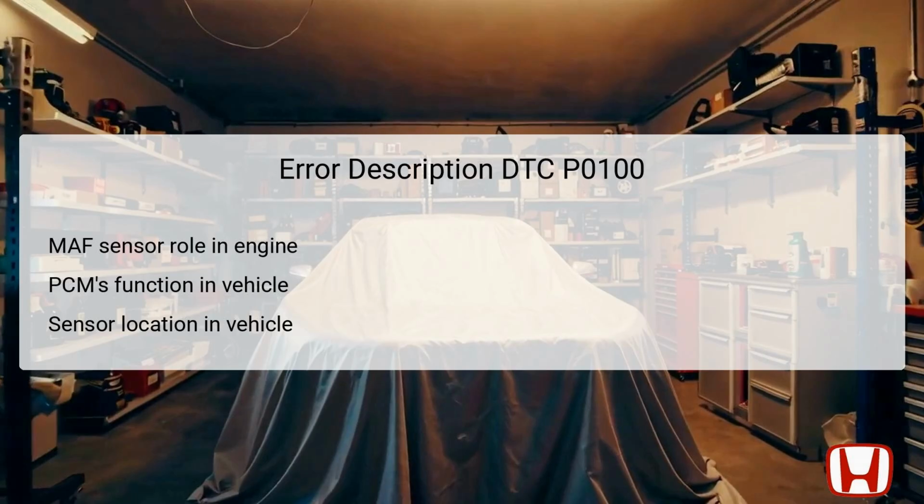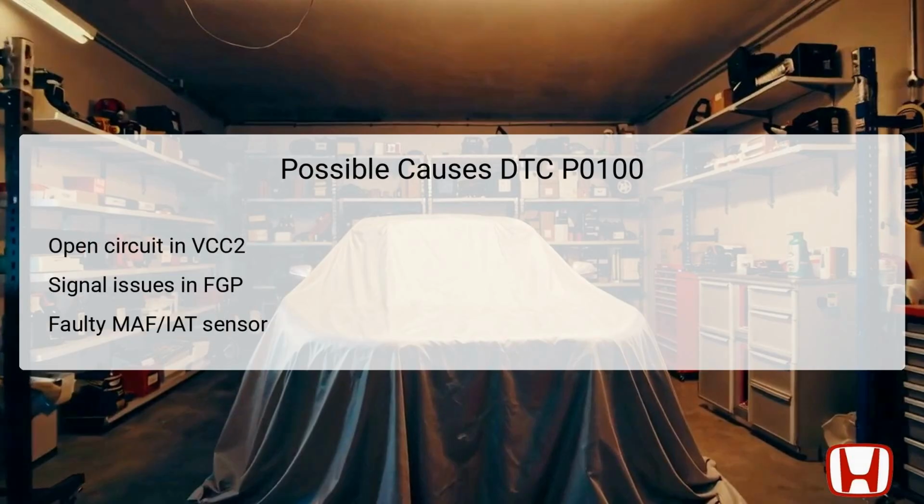If the MAF sensor's output frequency falls below a predefined value, the PCM identifies it as an abnormality and logs the DTC P0100. This can lead to various performance issues, underscoring the importance of the MAF sensor's functionality within the vehicle's engine management system. The possible causes for DTC P0100 include several specific malfunctions.